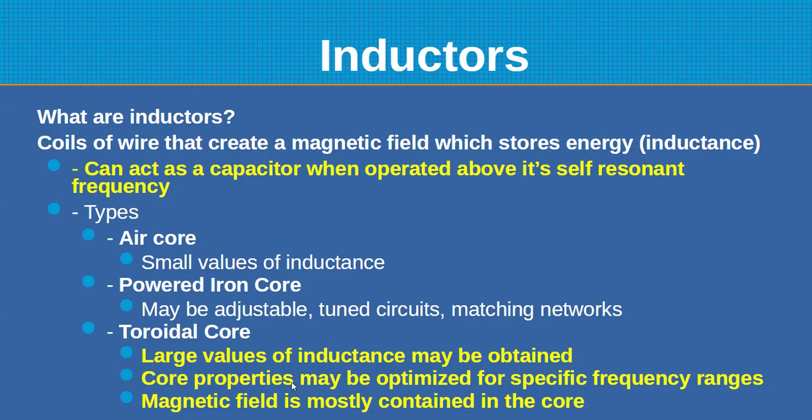And that's controlled by the mix, and the material is actually a mixture of kind of rare earth materials. They're various compounds, but they have specific mixes like 31, 43, 61, and they all have different frequency ranges where they will operate.